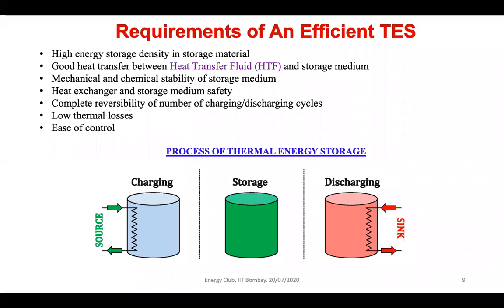The requirement of any thermal energy storage is that it should possess very high energy density per unit volume. Then the volume of the storage will be less and more energy can be stored inside that volume. Second, the heat transfer between the heat transfer fluid, which we will abbreviate as HTF, and the storage medium should be very good, so that when I need energy, I can extract it from the system, and when I want to store energy, I can readily store it in the system.